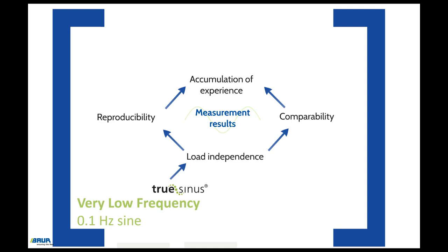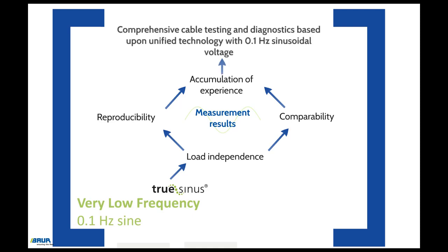A further advantage is the fact that the sine 0.1 Hz technology can be used for all meaningful measurement methods, such as dissipation factor measurement and partial discharge testing. Comprehensive cable testing and diagnostics is therefore based upon one unified technology with a 0.1 Hz sinusoidal voltage.